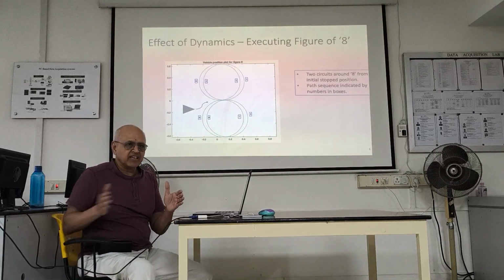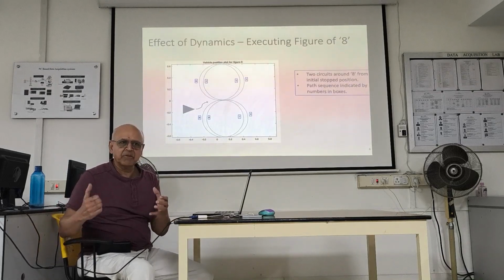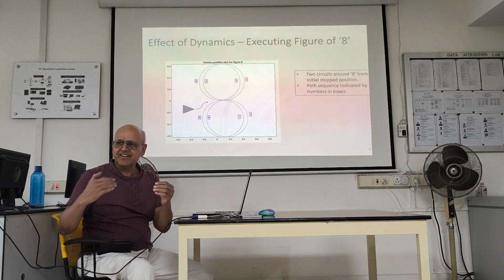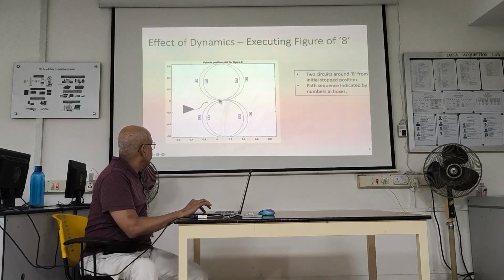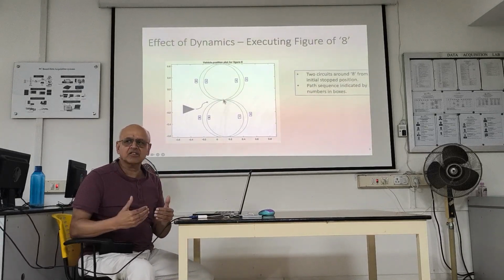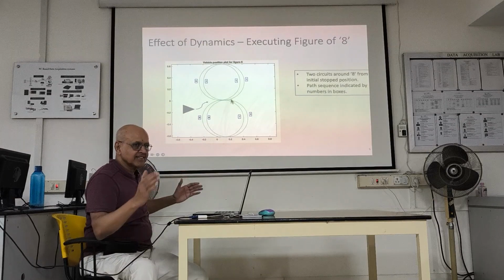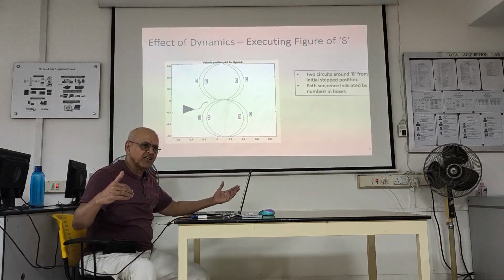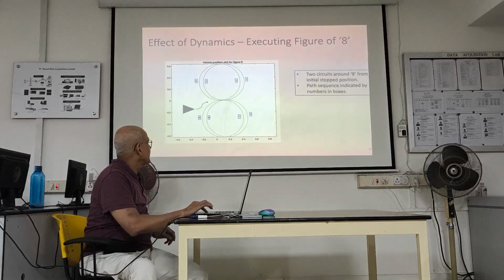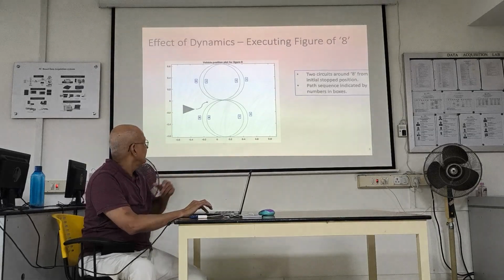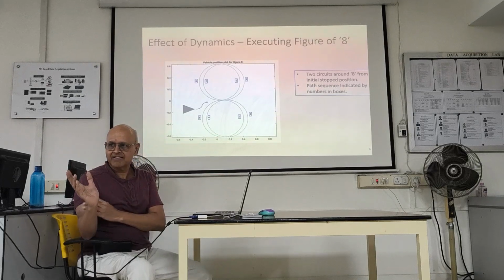So initially they'll be keeping pace, won't they? They both started at 0. They are identical runners. So they'll be running alongside each other till they reach the lower of the 2 velocities, correct? So the initial path will be a straight line. Do you get it? You won't be on the circle. So that's why you see like a flat line here. See? They're both keeping, and then the left wheel reaches its target velocity because it has a shorter distance to go. But the right wheel has to keep going. And somewhere there you get the ultimate circle. Somewhere here it has reached the target velocity. Are you okay with that?